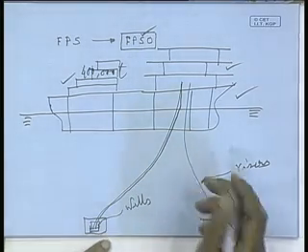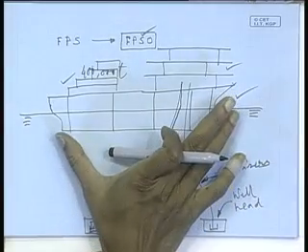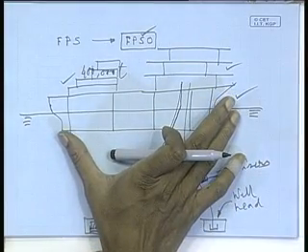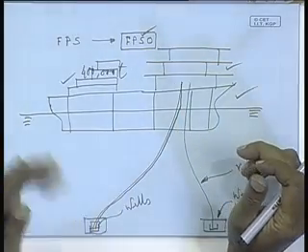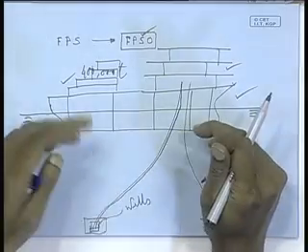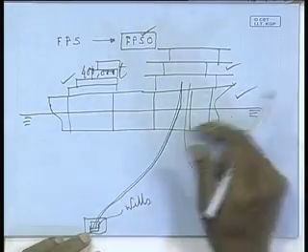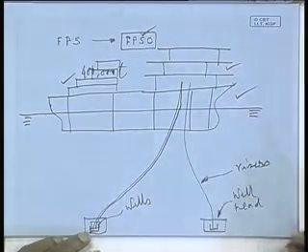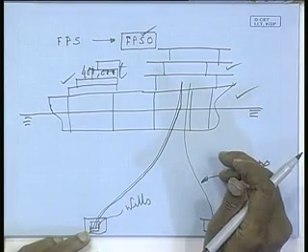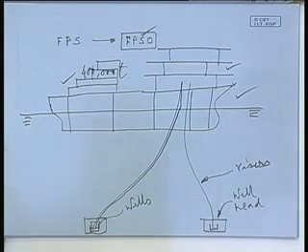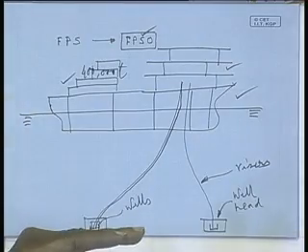Also, this FPSO is totally free. So, construction wise, there is no bending moment problem. In all the other things, there was some movement of the structure, all those problems were there. Here it is only for exploration, you are only pumping oil. These riser pipes are flexible, but still it has to have some kind of means of anchorage, some means of position keeping, such that it does not move out, does not sway out too much. If it heaves with the wave, no problem, because the pipes are flexible, you have enough length to take care of that.